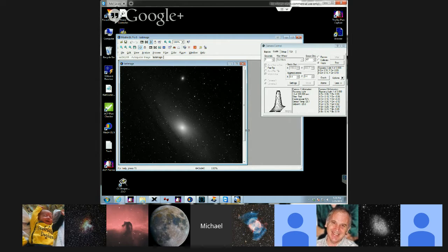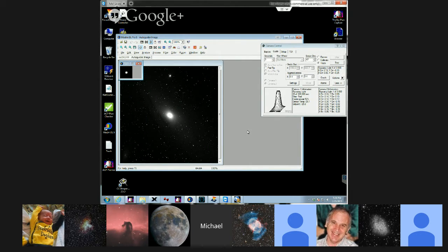And the concrete pier was extremely inexpensive to pour. I had a guy, on cloudy nights, who told me how to do it. You just take a hole digger and go down about 4 or 5 feet. Went to Lowe's, bought what's called, I think, a Sonotube. It's just a round tube. Stuck it in the hole, put some rebar in it, leveled it out, and then left some bolts for the correct pattern for the mounting plate up above, and let the concrete dry for a week. Set the mount on it, and I had a permanent installation that probably cost me less than $100 to set up.